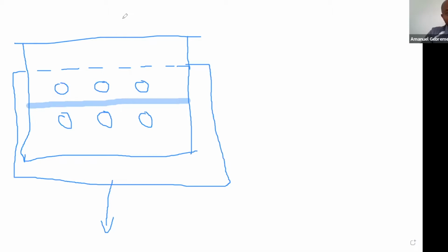Then a different question might come up: what do I do for shear or tension through this area, which is right along the bolt holes, because that's a reduced area, and you would typically check that for the fracture limit state, which is essentially an ultimate limit state that checks for tensile rupture on that net area. So people are quite familiar with checking these types of limit states.